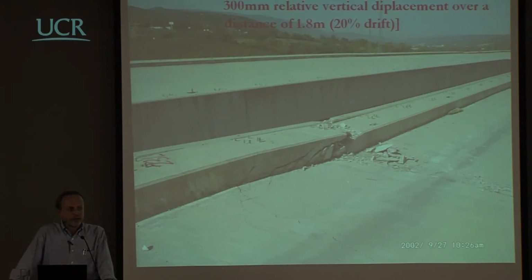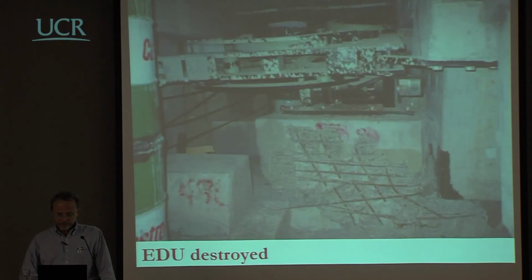To explain how this part of the bridge is still there, you should look at problems in large displacement, considering the capacity of this part of the structure to act as an inclined strut and tie system.